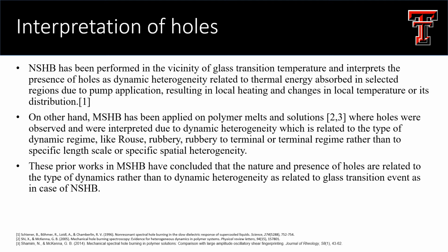On the other hand, mechanical spectral hole burning has been applied in polymer melts and solutions, where holes were observed and were interpreted due to dynamic heterogeneity, which is related to the type of dynamic regime like Rouse, rubbery, rubbery to terminal or terminal regime, rather than to specific length scale or specific spatial heterogeneity. These prior works in MSHB have concluded that the nature and presence of holes are related to the type of dynamics rather than to dynamic heterogeneity, as related to glass transition event as in case of non-resonant spectral hole burning.